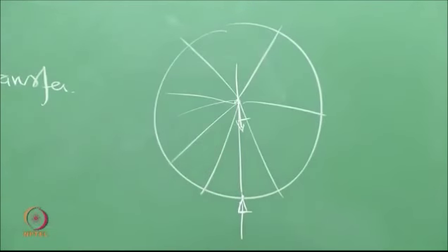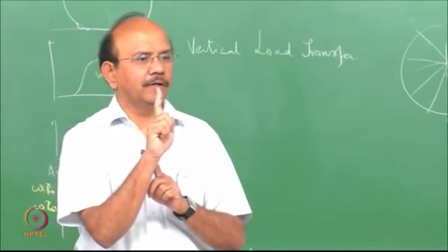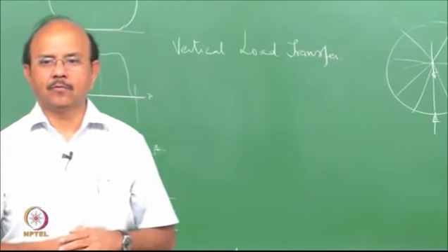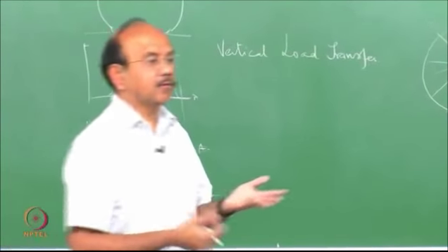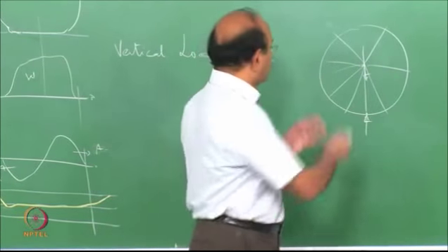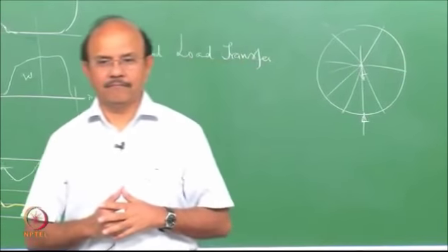the spoke, as you know, is a very thin piece of steel. If you subject that spoke to compression, what is going to take place? It's going to buckle. So the spokes are assembled with tension.